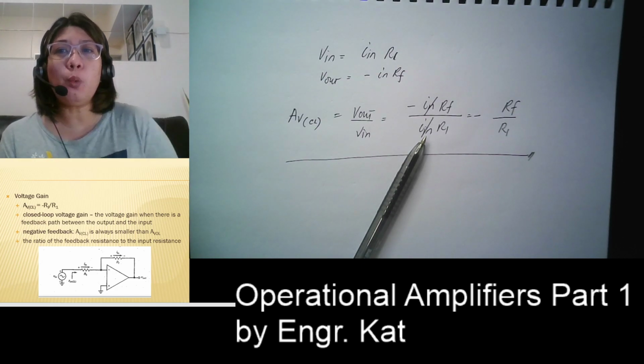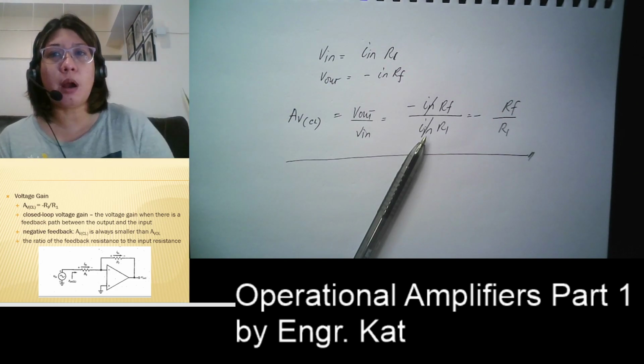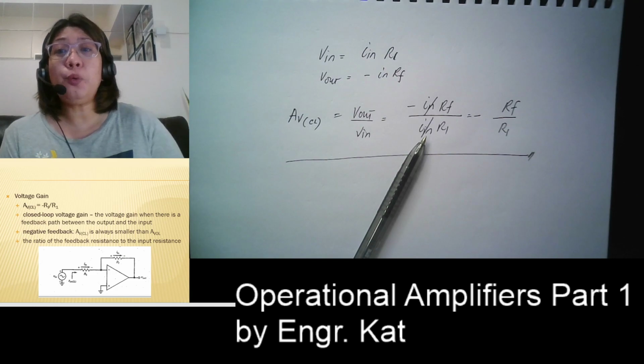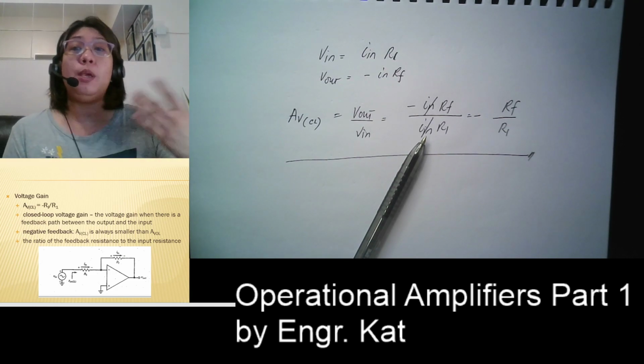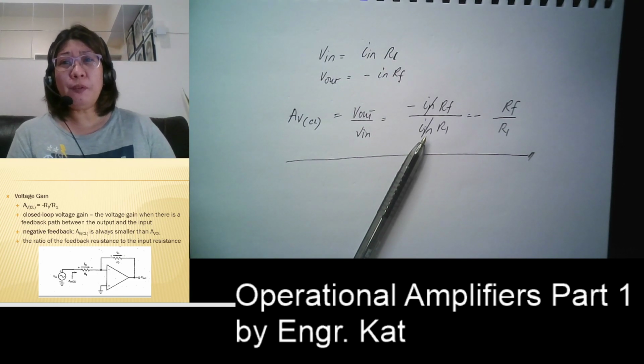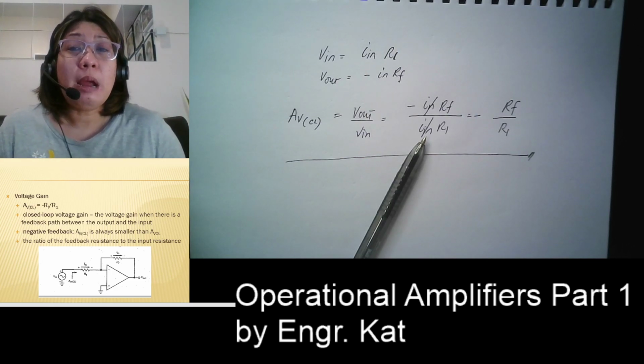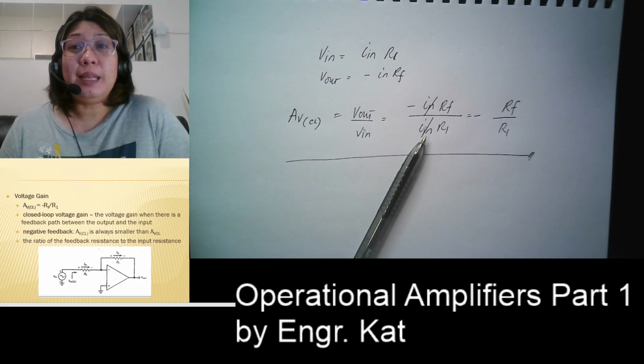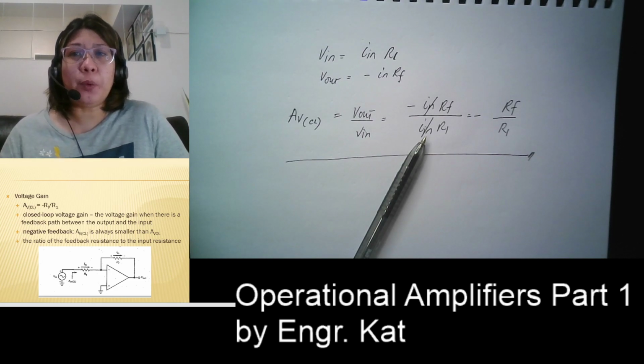What will be your R1, your R2, your RC, your RE? You will start with the DC analysis, then go to the AC analysis before you can even solve for your gain of 50. But this is a very straightforward approach.